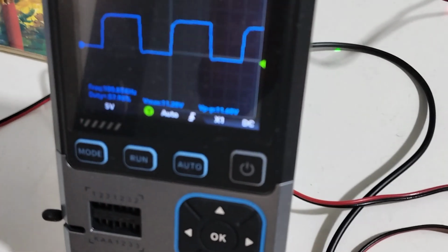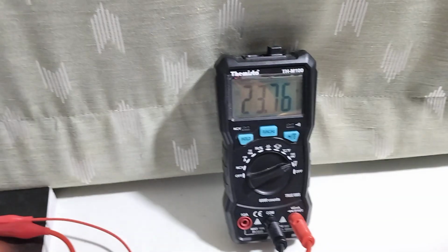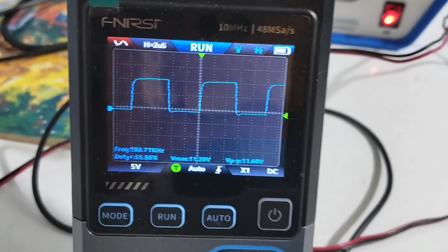Of course you can tune this better, and you can see here the duty cycle, which was 56%, increased to about 59. And if I remove this again, it goes back to 23. So you can see how it adjusted, and we're back to the original duty cycle here. And that's how the closed loop is working.